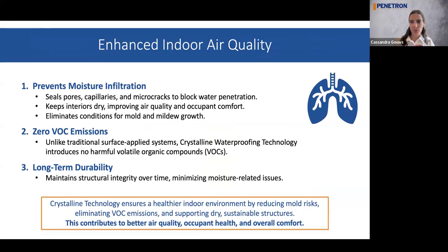I'm sure some of you thought in the beginning when I mentioned crystalline technology can enhance the indoor air quality, well, how can it do that? It does that because it prevents moisture infiltration into your buildings. Because you're preventing moisture and water from getting into your buildings, you're eliminating conditions for mold and mildew growth, so that improves the air quality.